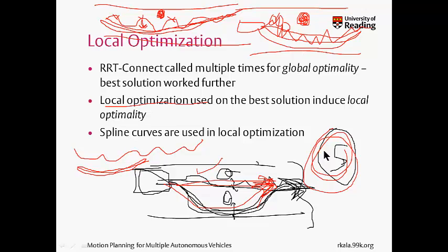The second thing it will do is select whether this path is good, or this path is good, or this path is good. Based on the cost function that I provide, it will select which one of these paths is good. And how it does that is, suppose there are 4 points that this trajectory represents, joined by a spline curve which produces the trajectory. It will try to move each of these points a little left, a little right, a little up, a little down, and see what is the best setting for all these points, and correspondingly it will be able to select the best out of all these trajectories.